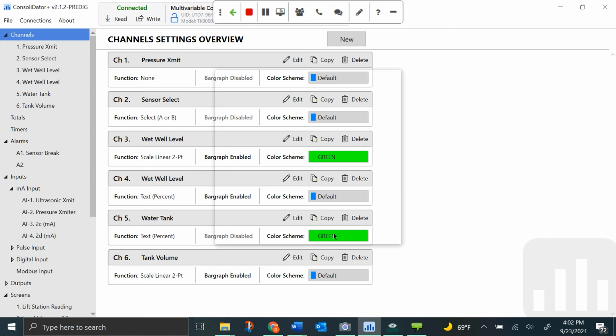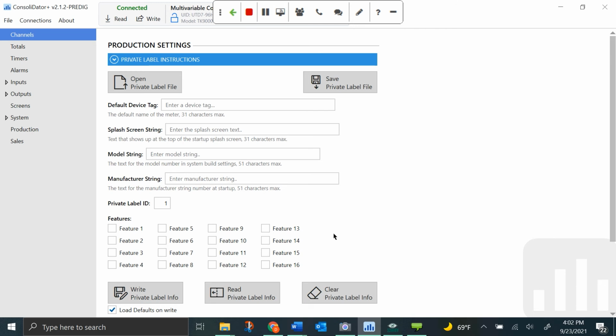So once I have that done, I click OK. And now this is a raw software, so there's nothing on it. This is just plain. The first thing we want to do is set up an input. Anytime we want to set up some new object or create something new, we're going to pick out of this pool of objects here. The left side of the screen is where we're going to grab everything. So I'm going to come to inputs, click this little button here that drops my options down, and I want to set up a milliamp input.